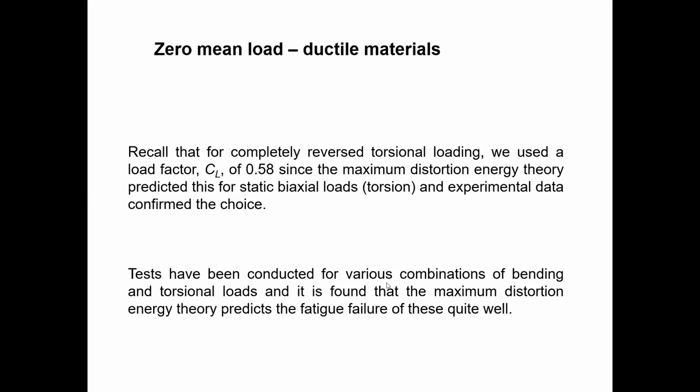So at that time, shear stress should be equal to 0. You can apply the maximum distortion energy only for the principal stresses plane, if you remember. So you need to find the principal stresses at that point in the Mohr circle. Also you can see the shear stress will be 0. So this is from the previous lectures. Okay, so remember.